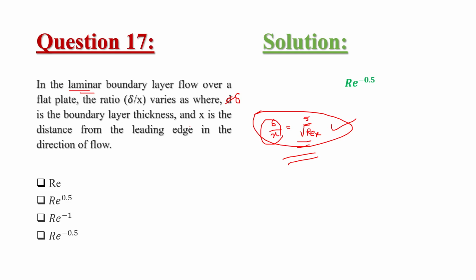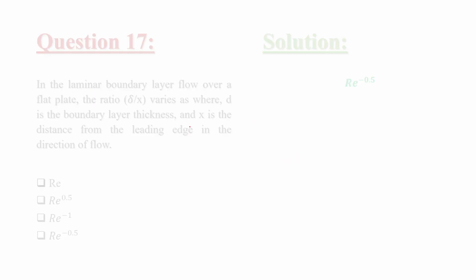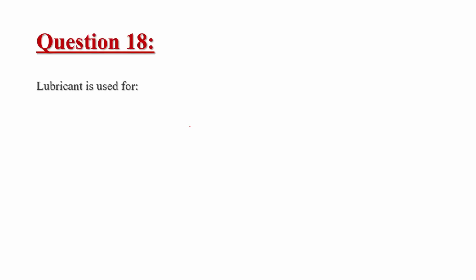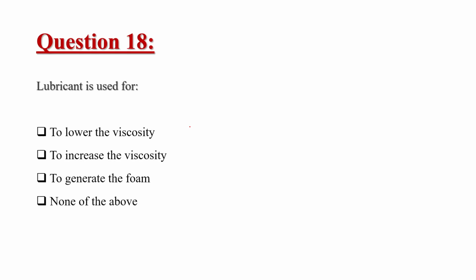So the velocity is equal to the sum of these two components. This is the deviation, that is the u dash, and this u dash is called the fluctuating component. That means how far the velocity is from this mean condition, how it is fluctuating from the mean condition. So this is the fluctuating velocity or the u dash component of the velocity.